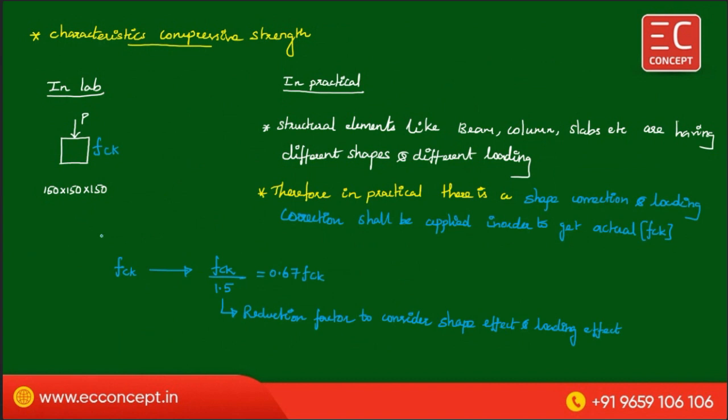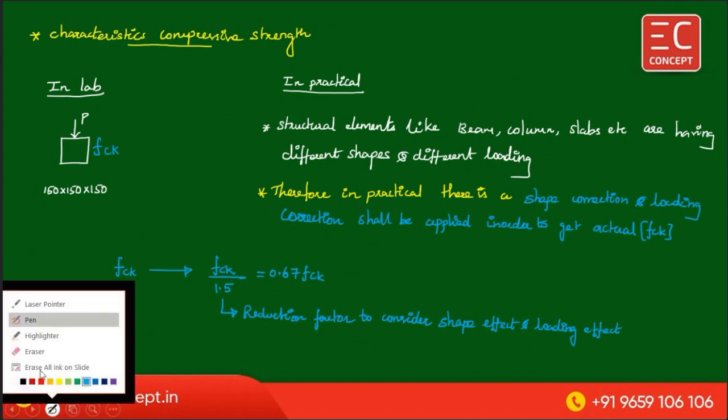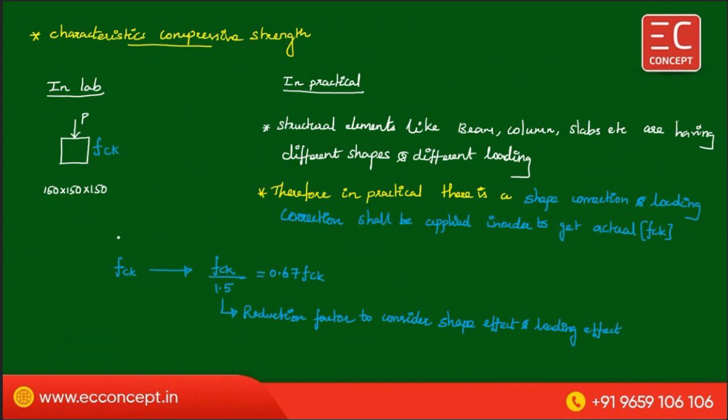In the lab, we use FCK as the characteristic compressive strength. In practical, we will use 0.67 FCK.